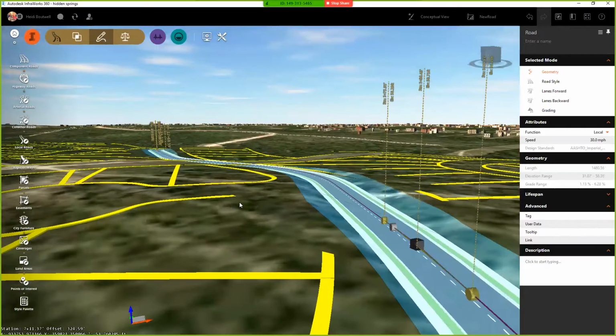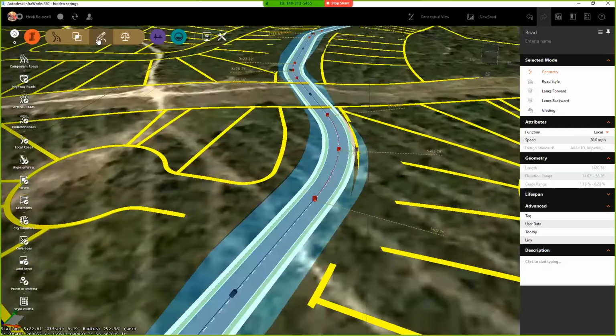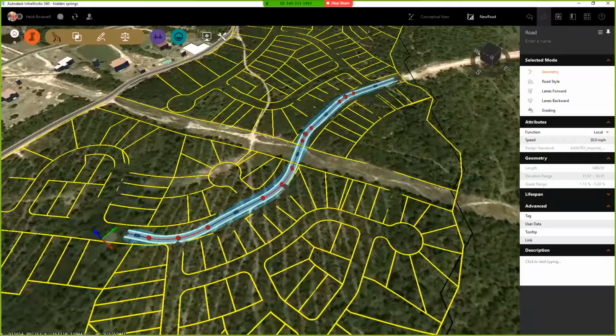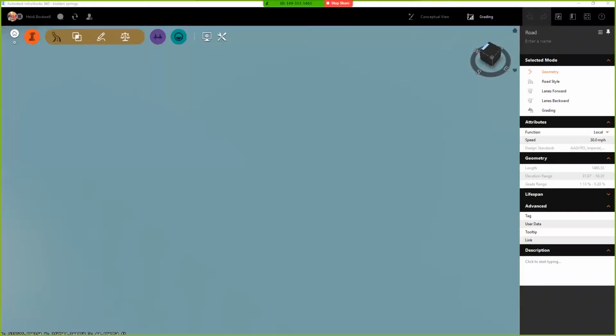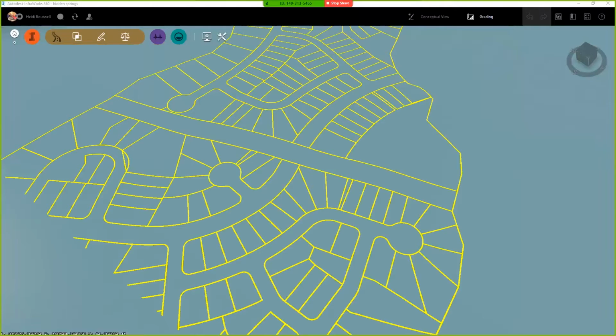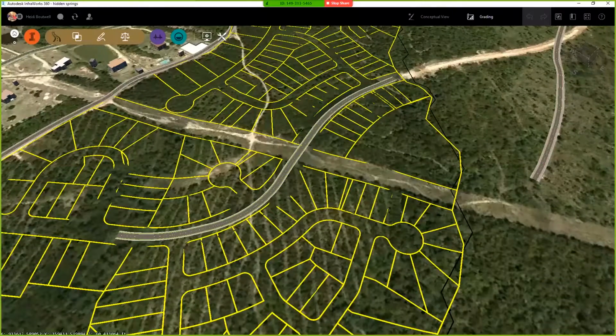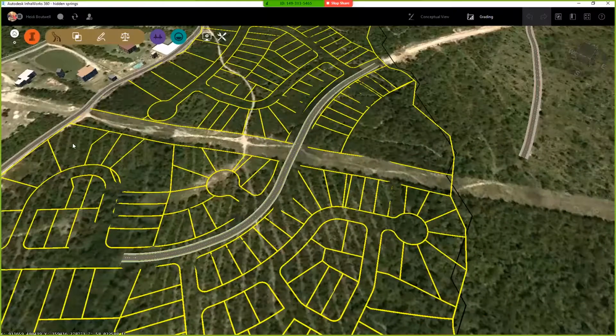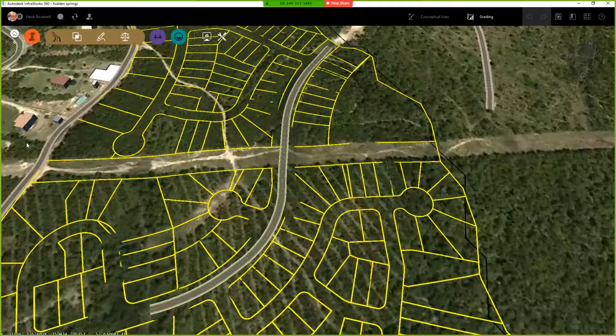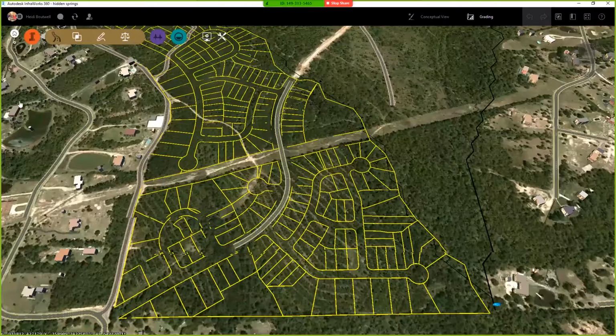So adding roads is quick and dirty, great for presentations. Now that I've got my roads out, what if I want to do some standard grading in these lots? We'll flip over here to my grading one. The beauty of making proposals is I can draw a bunch of stuff here, switch over to another proposal, and this is remembered in the original proposal, and the other one has other stuff already done in it. Okay, there we go. All right, local roads.